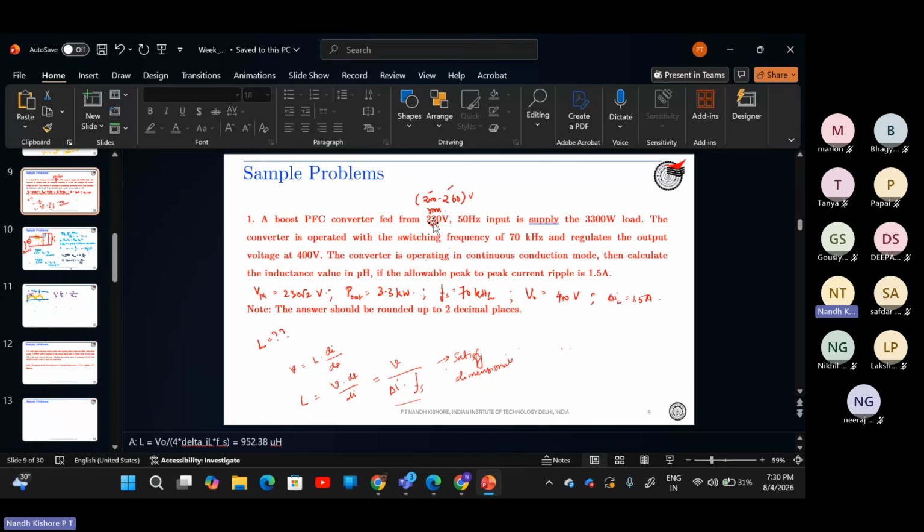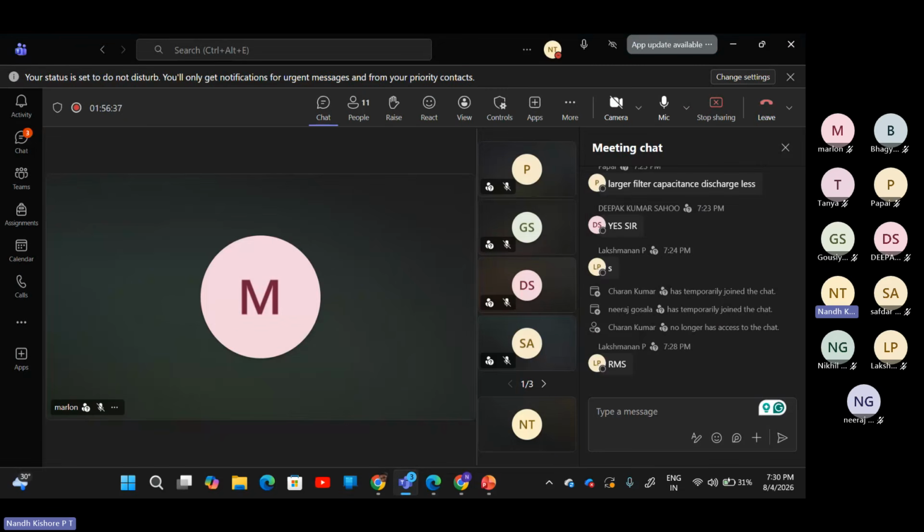At some point you will see that there is a voltage sag, and you get even 205 or 200 or 195 volts. At some places you get 230 volts properly and so on. So you would have to design your inductor not for the ideal rated condition, but for the worst case condition. So if they give you a range of input voltage, you have to know what voltage should be taken. Is this understood? I hope this is fine.